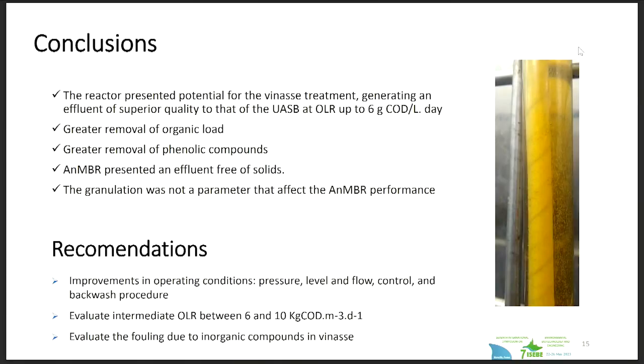What I can recommend is some improvements in the operation conditions, such as better control of the pressure level and flow, and also using a backwash procedure instead of the relaxation process to avoid fouling in the membrane. Also, to evaluate some intermediate organic loading rates between 6 and 10, and the impact of inorganic compounds on the membrane fouling.